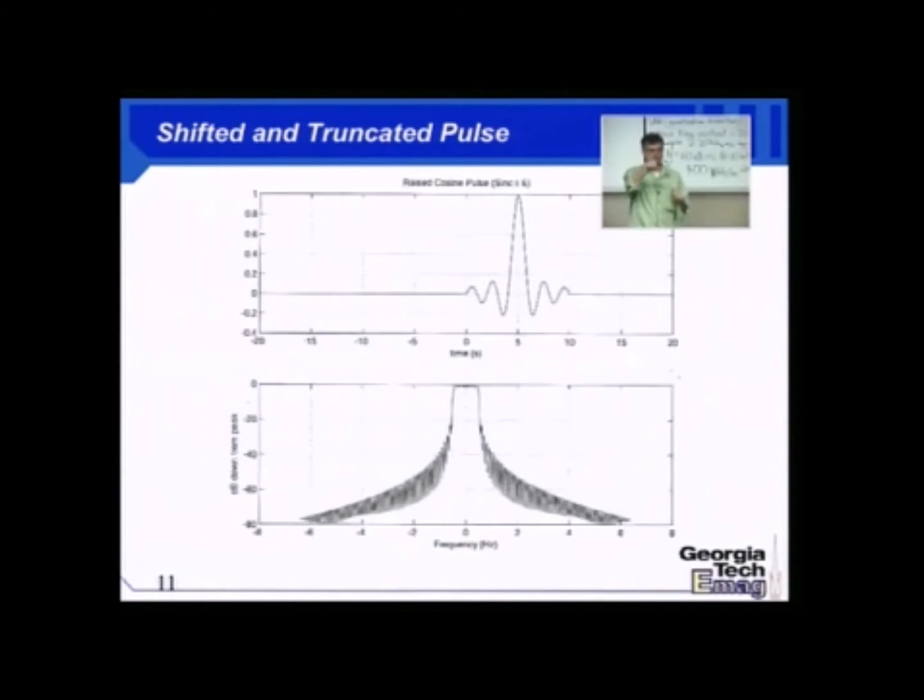Do you have any questions? Yeah. You still need more time to generate that pulse. That's right. It's a trade-off, right? Here, now I have to have hardware that can support the generation of a longer pulse. I need to start ramping up ahead of time. Now I'm introducing, in this case, about 5 cycles of latency.